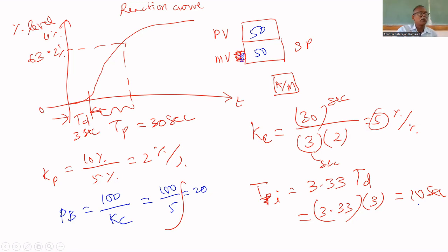If for any disturbance the controller controls the process, then it is called regulatory response. Now, after changing to closed loop, you are changing the set point. Now it is in closed loop. You are changing the set point from 50 to, let us assume, 55. What is the error now? 5%. The controller will take necessary action to bring the process to 55. After some 20-30 minutes, the level will automatically come to 55 and remain at 55. This type of response is called servo response.